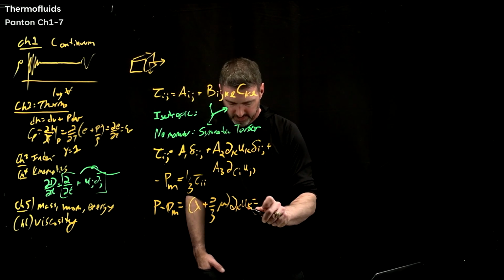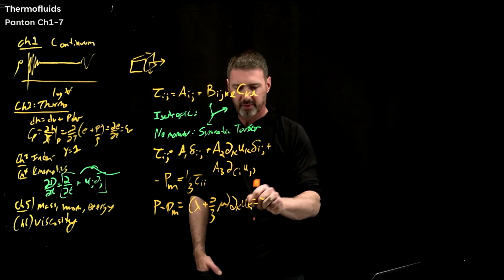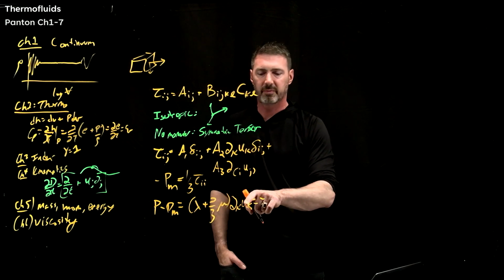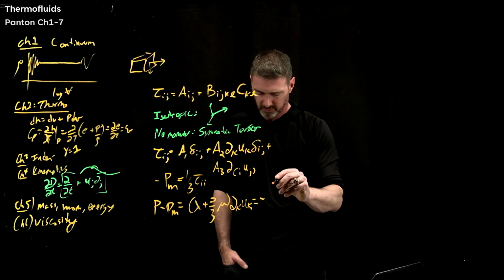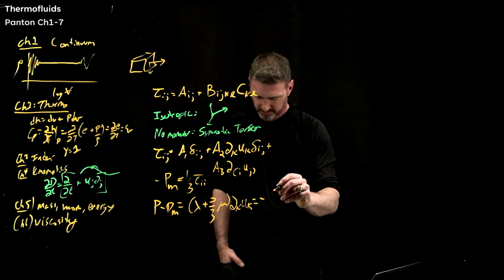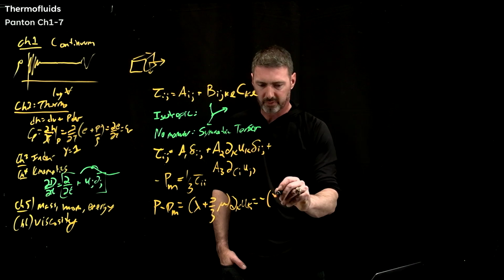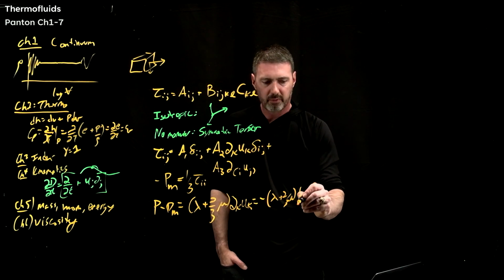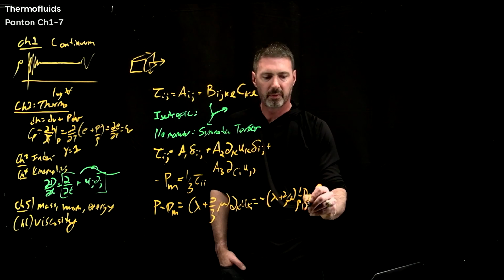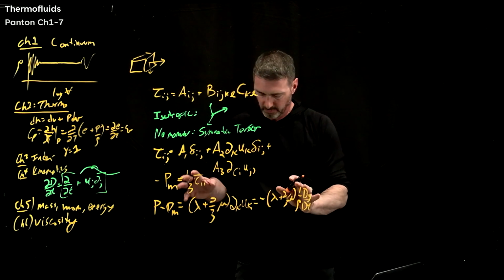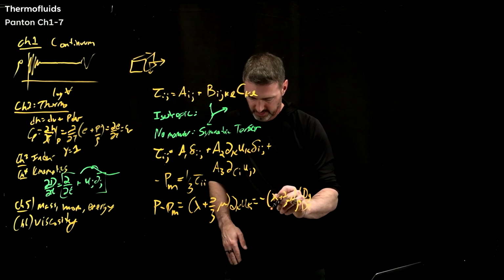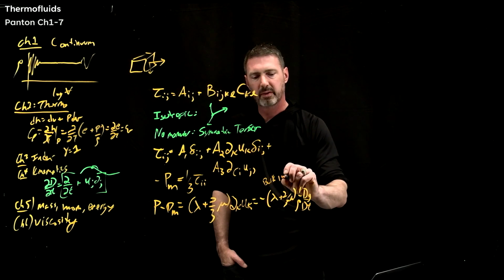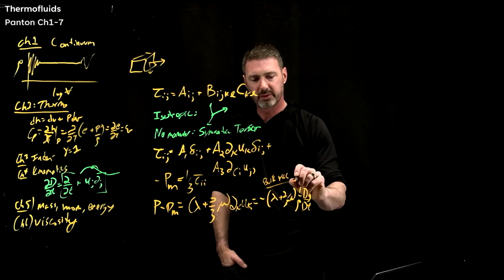But then if you apply the definition by conservation of mass, even for a compressible flow, that is then equal to lambda plus 2/3 mu, and you have 1 over rho times the material derivative of rho. That's actually conservation of mass. So this whole thing is called bulk viscosity. This entire term.